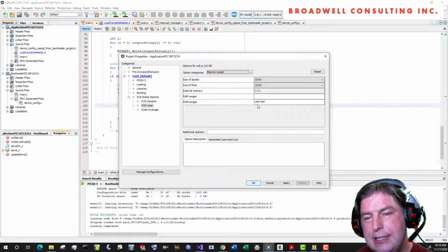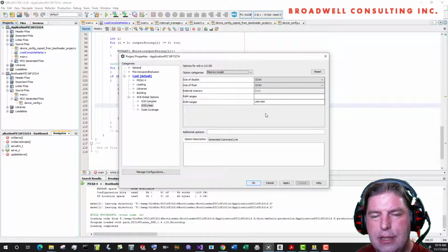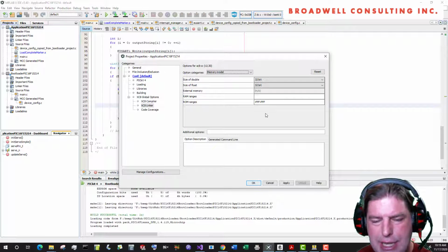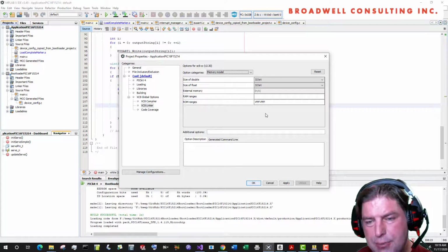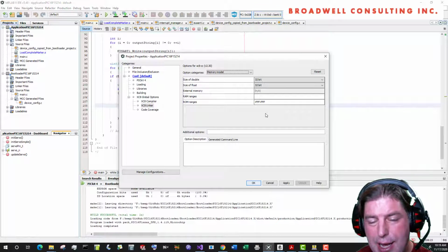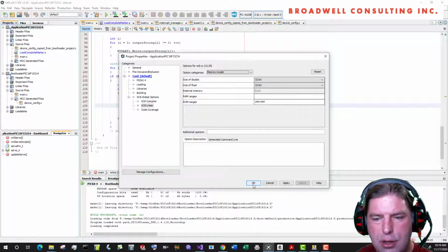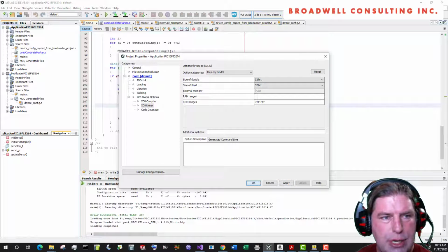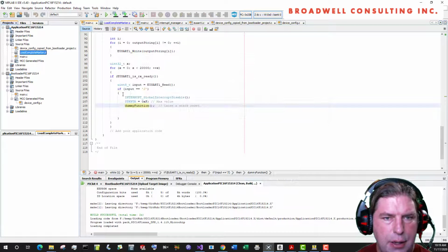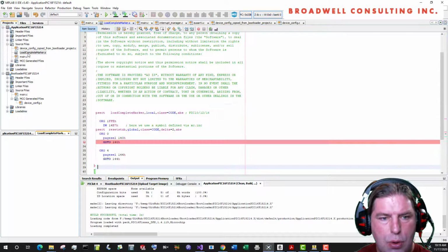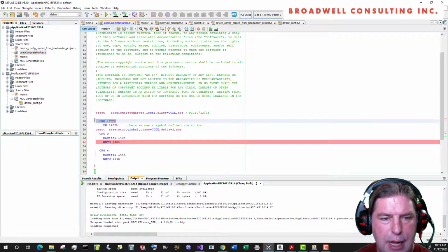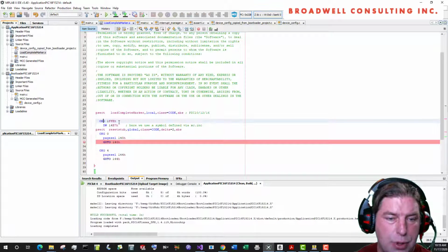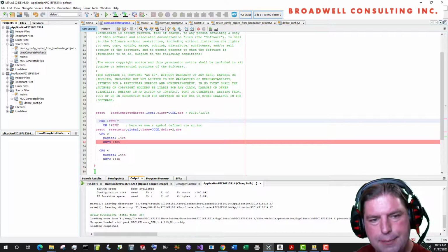And what that says is from word FFF to word FFF, the linker is not allowed to use that location. So if it wanted to put something there, it won't, which leaves that word for me to explicitly fill in using this org address right here. And this is in bytes, the other one was in words.